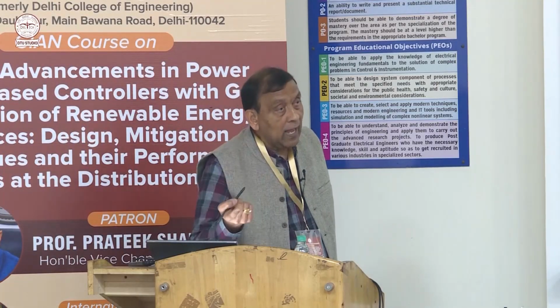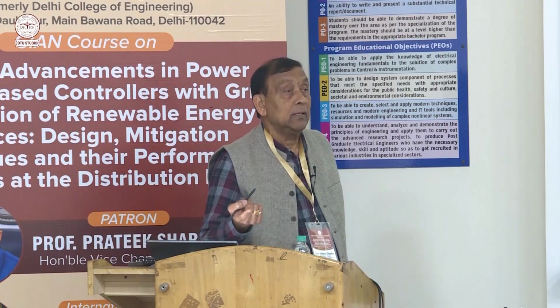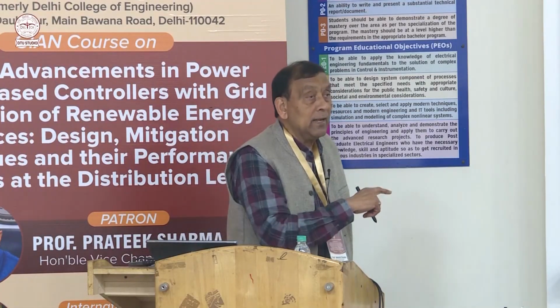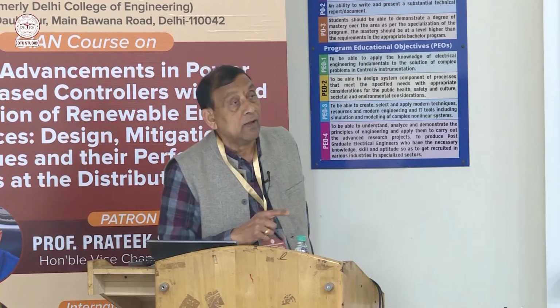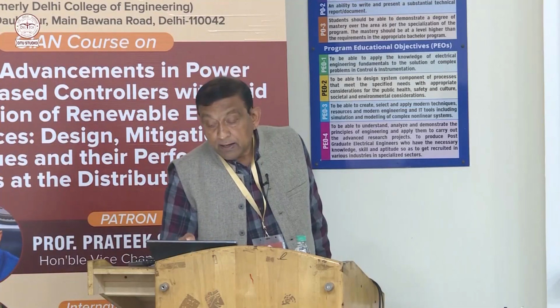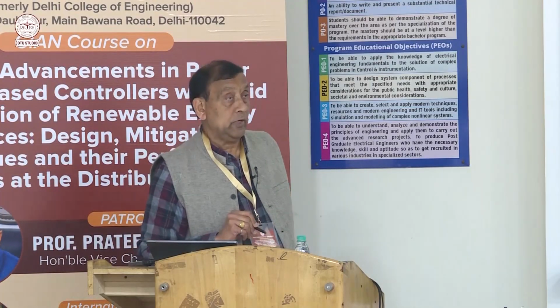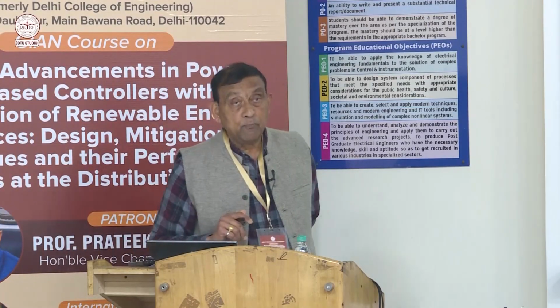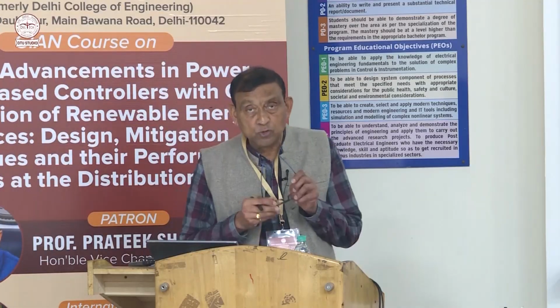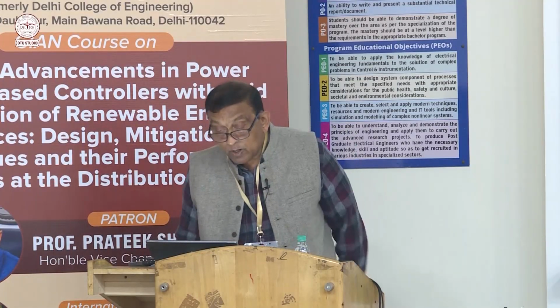And 5th harmonic is a negative sequence. When it goes to the primary side of the transformer to the network, it will get a plus 30 degree phase shift. So this is very important to know. Later on we will use this technique for harmonic cancellation.